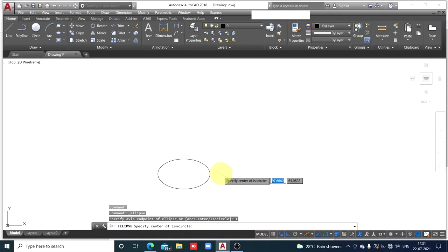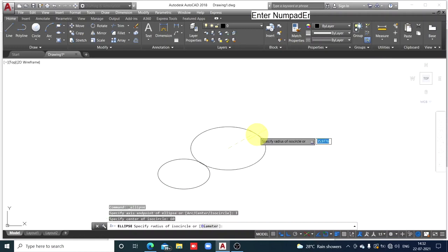Move the cursor to this earlier circle. There is the center. Now AutoCAD is showing you the center of this ellipse. So move the cursor to the ellipse, select that center, but don't click on it. Just trace that point, that is, get that tracking line, and on this tracking line it is the length axis. At a distance of 60 millimeter from the center, 60. Enter.